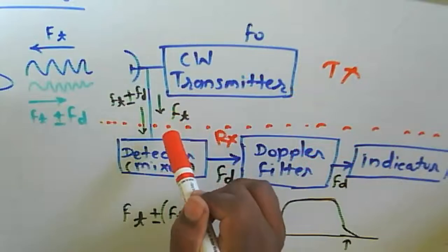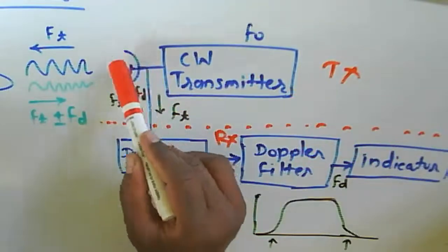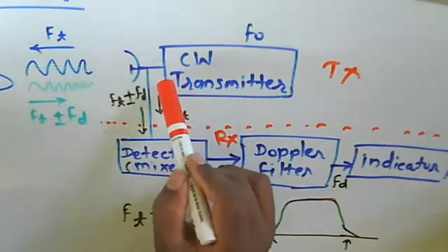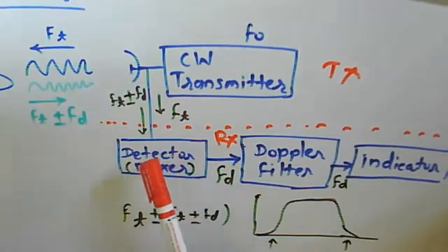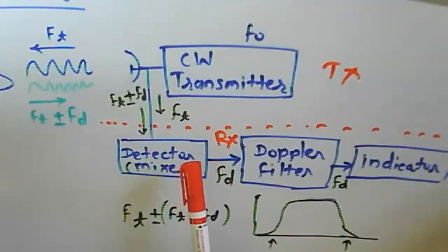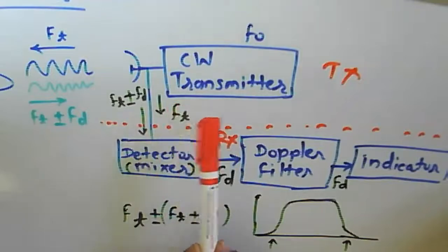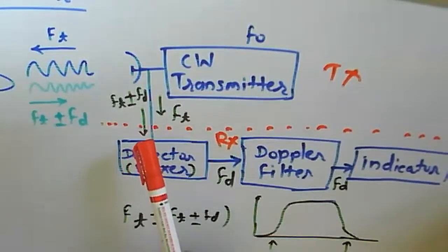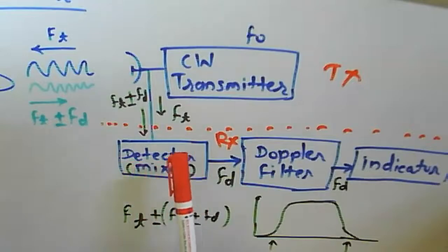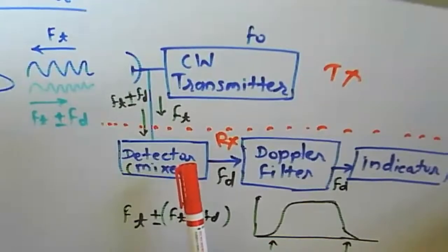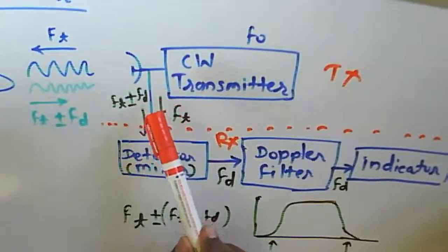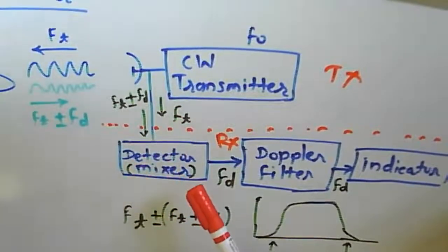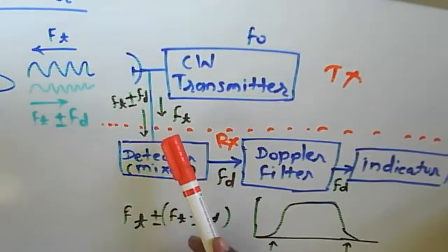But what happens in general if we use the same antenna for the transmitter as well as the receiver? Some portion of the signal from the transmitter may reach the detector. If the transmitted signal is large and reaches the detector, it will damage the receiver circuit. So the signal coming to the detector should be of low value.